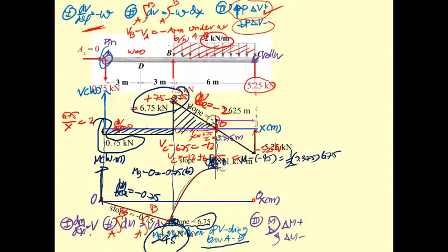Take this one out. Okay, this is slope equal to 0. You get this for 6.891. Okay, that is going to be the value of the moment at this point, 6.891. And now this is 0, but you have to check the slope here. The dM/dx here is going to be this one, minus 5.25. And then the curve is going to be coming in this way.